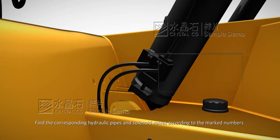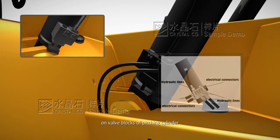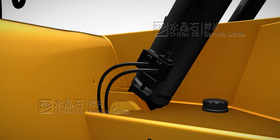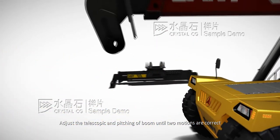Find the corresponding hydraulic pipes and solenoid valves according to the marked numbers on valve blocks of pitching cylinder. Connect the oil lines and electric circuits. Adjust the telescopic and pitching of boom until two motions are correct.